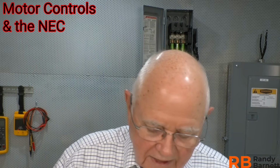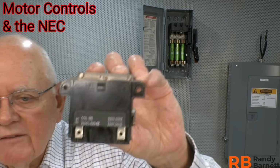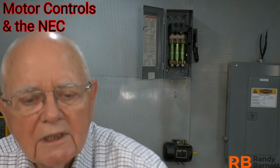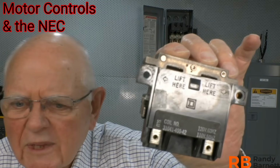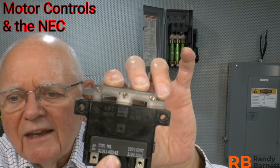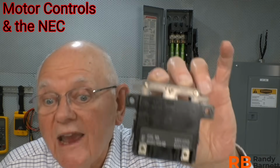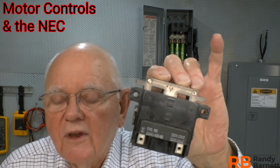I just replace it. Let's take a look at the coil. So this is my coil of wire, and I've got some ratings on that coil, and it says it's rated for 120 volts, 60 hertz, 110 volts, 50 hertz, okay? But it doesn't give me a current rating. There is a number over here that I can look up for the manufacturer, and no problem, I got it very easily. It's 2 amps. So when this coil is energized, it draws 2 amps of current flow. Great.